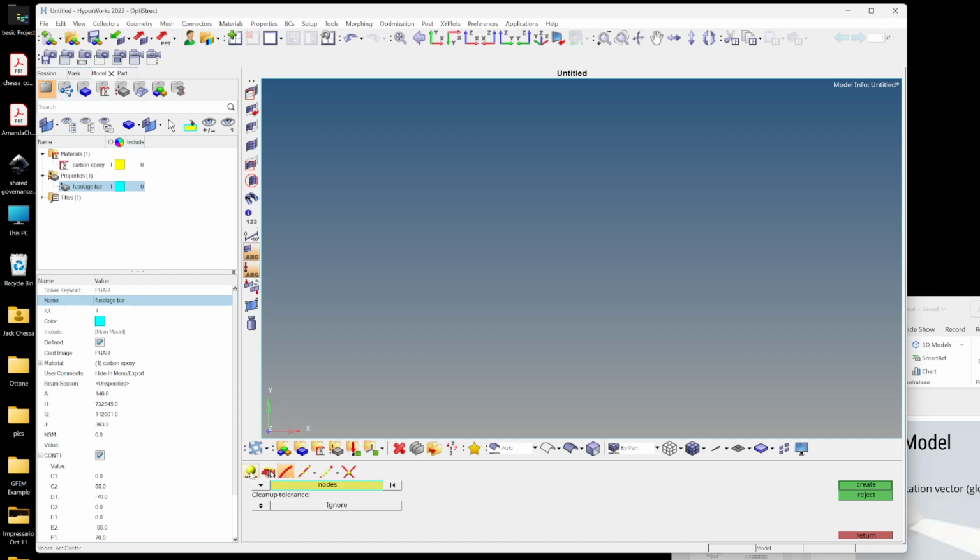Now for us, we're going to just type in the coordinates. So if you don't see this, make sure you click on the little tennis ball icon here, and it'll show up, okay? So we put in 0, 0, 0. We'll create. There it is down there. All right. Next, we'll put in 4800.